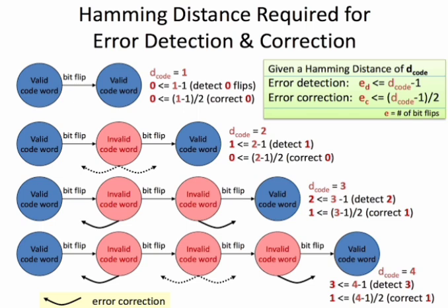FM radio broadcasting utilizes the frequency band 88 to 108 MHz. The carrier frequencies are separated by 200 kHz and peak frequency deviation is fixed at 75 kHz. Intermediate frequency FIF in case of FM is 10.7 MHz. Polarization is horizontal, wave propagation is space wave propagation. In case of TV signal, picture carrier is VSB-FC modulated, color subcarrier is QAM modulated, and sound is FM modulated.